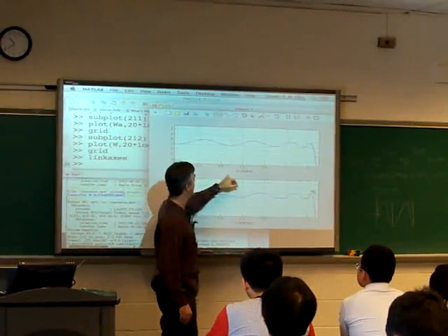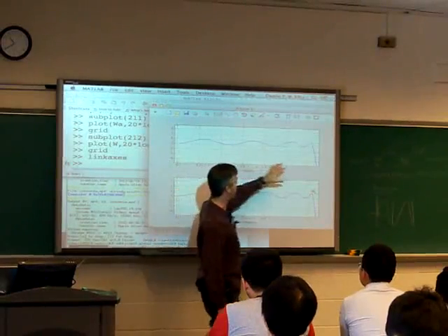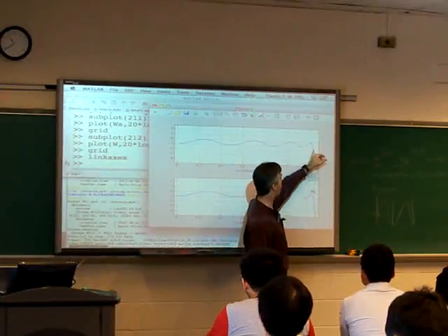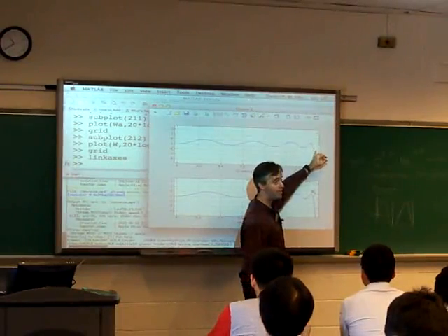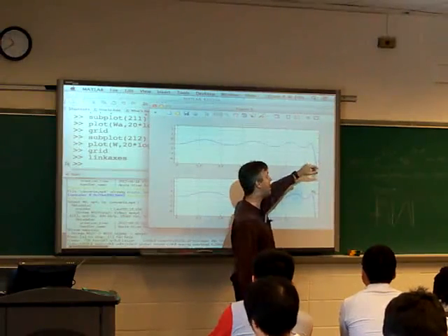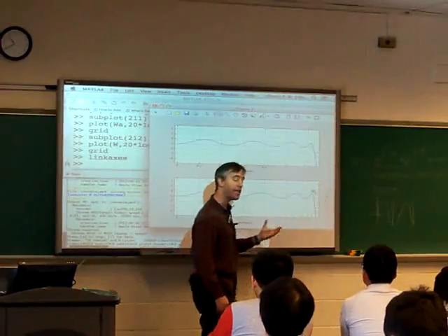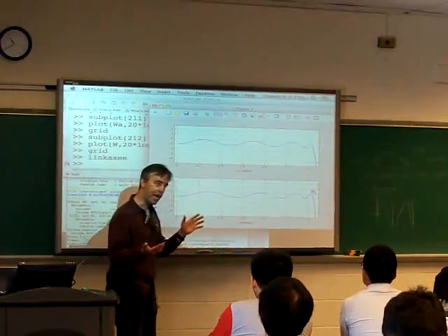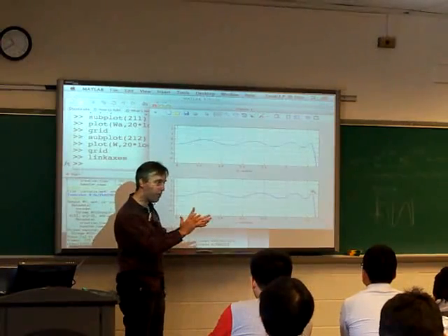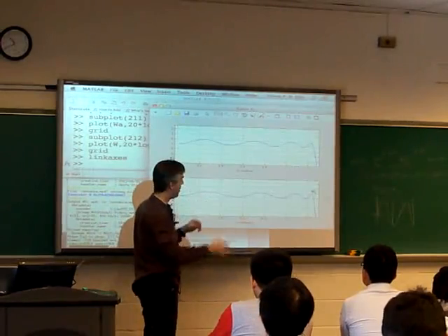Here's the big omega radians per second, the pass band, which, just because I can scale it, I've arbitrarily scaled to have the same numerical value here, even though it means something different. And again, we see 1, 2, 3, 4 peaks because the bilinear warping will map all of those features into the same part of the pass band.